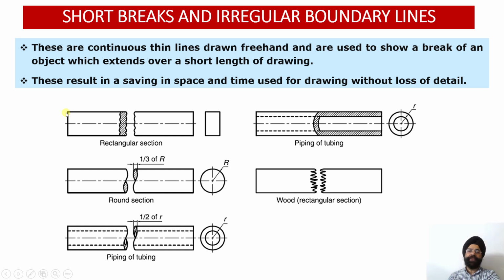So half an inch or maybe less than that. If I have to draw that particular diagram onto my drawing sheet, if I reduce it by 200 times, that 20 millimeter divided by 200 times reduction will give me half a millimeter thickness. So I will not be able to draw the actual dimension details onto my drawing sheet.